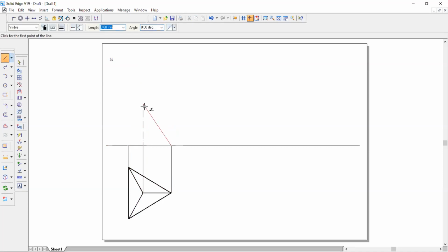Excess amount of axis which you have drawn, you just trim this. Draw the line here. Draw the line here. Change this whole thickness except this axis line to 0.5. Now it says the edge containing the corner is inclined to 50 degrees. So edge containing the corner, you can say this is the edge, this is the edge. 2 edges are there.